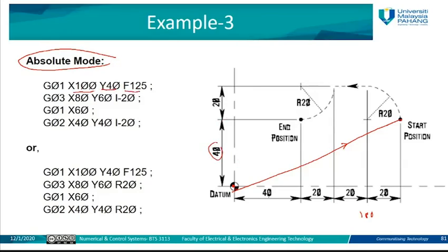And for the speed, the feed rate, we said there is a list or a table for feed rate. It depends on the type of material for the tool, the type of the work piece, and so on. As you can see in our example, we just put one of these values. There is a table of the speeds, and this feed rate and speed are calculated based on several parameters related to the tool diameter, the speed, and so on.